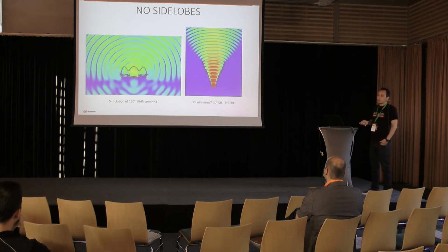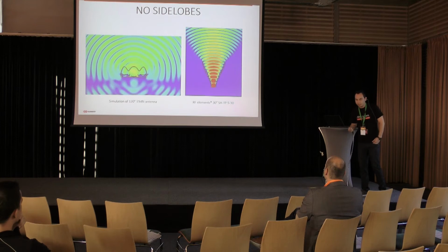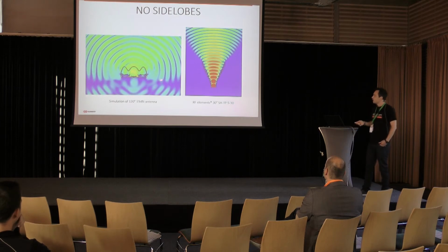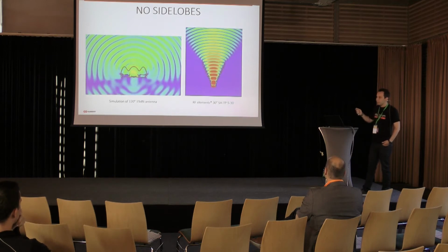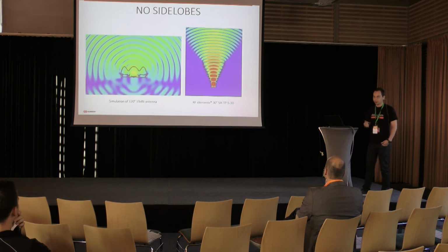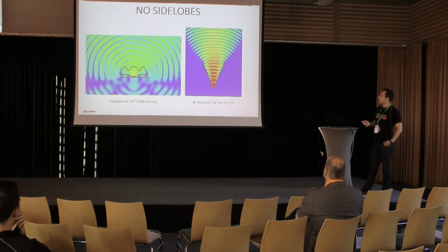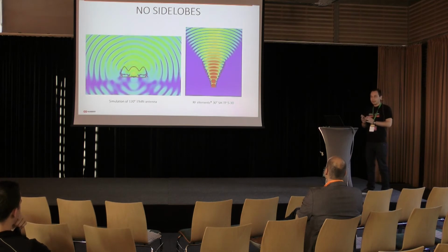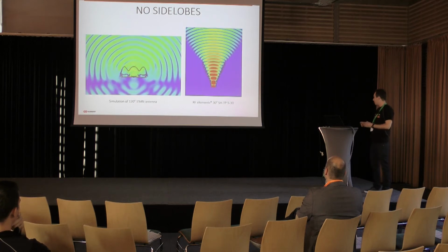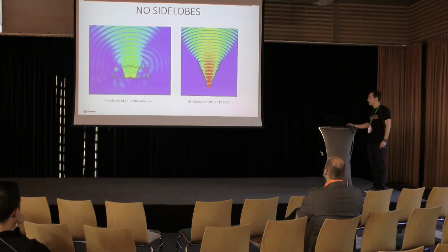But when you collocate, let's say, 4 APs in one tower, this is what makes your huge problems, because the back lobes and the side lobes are affecting the other APs around. But on the other hand, if you check the shape of the beam of symmetrical horns, the signal is dedicated only to the angle where it is supposed to go. So you are not spreading any side lobes and any back lobes to the other APs.